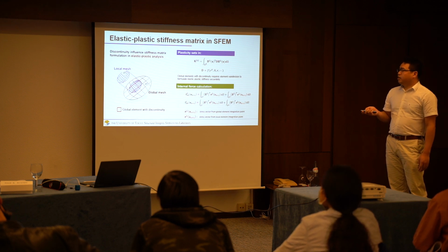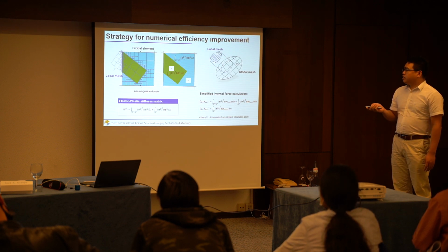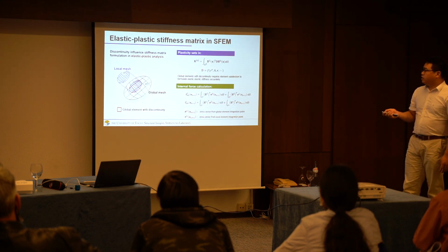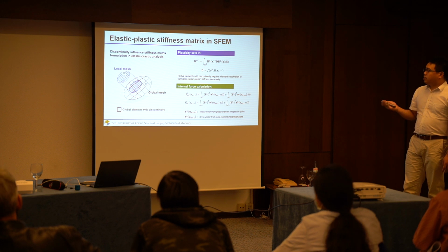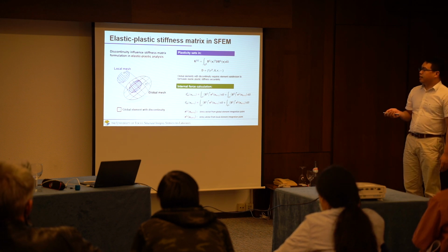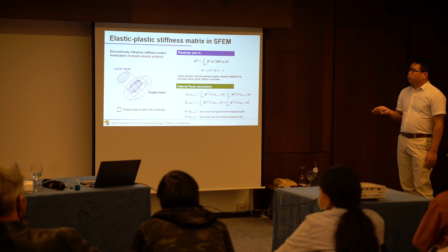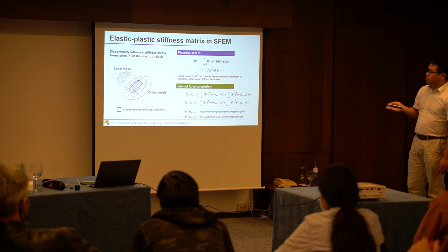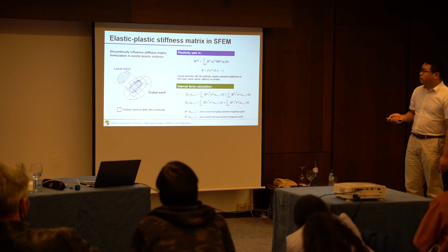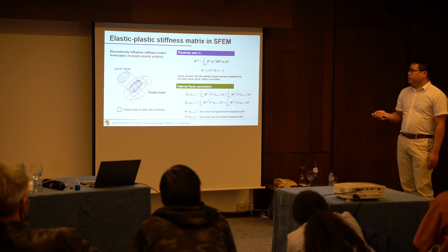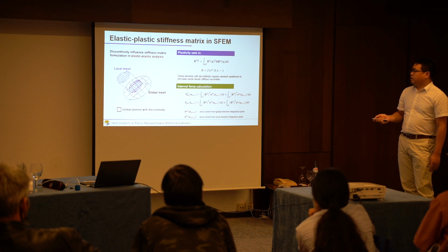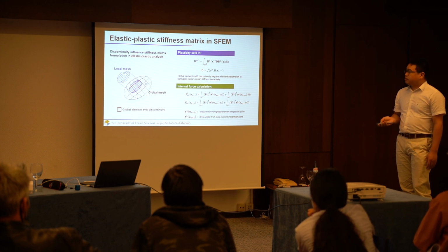After applying element subdivision to both the global element and the local element, we can calculate the internal force in elastic plastic analysis. Note that in the elastic plastic analysis, we superimpose the strain and update the stress, using the return mapping method or cutting plane method. For the calculation of internal force, we need to calculate the stress from the global mesh, sigma G, and sigma L from the local mesh.